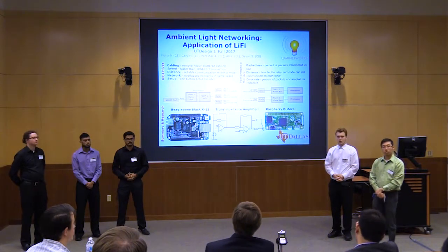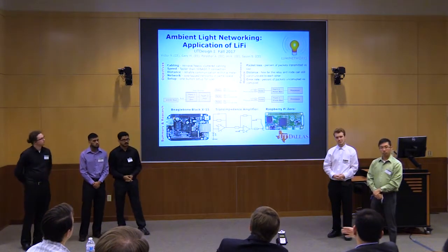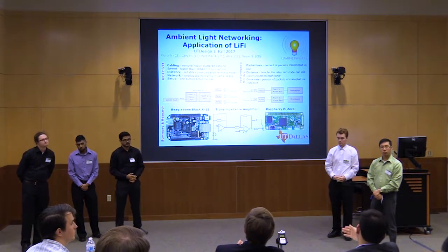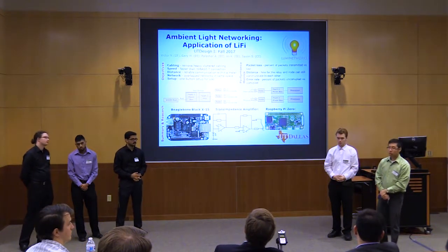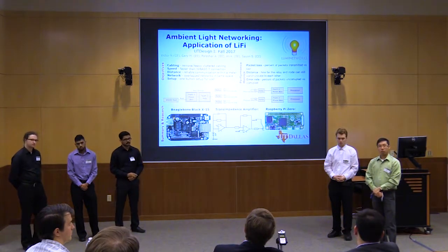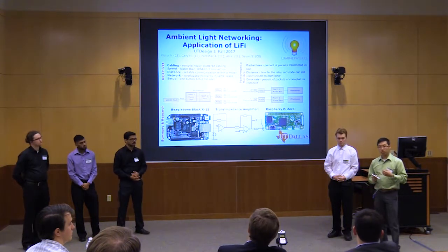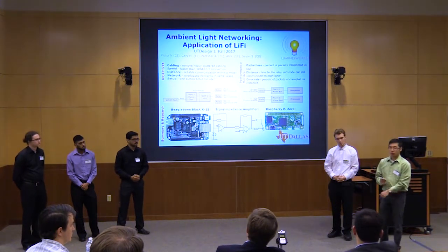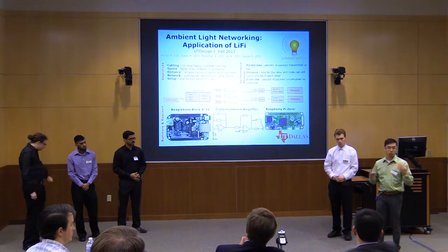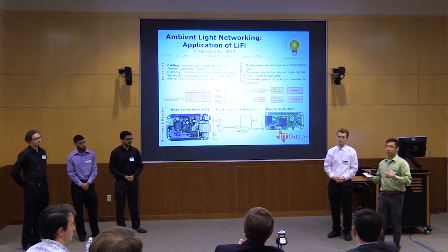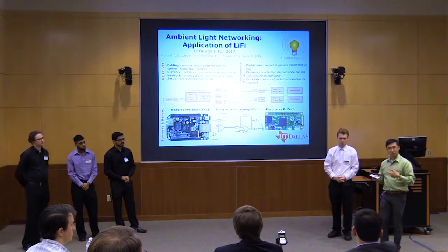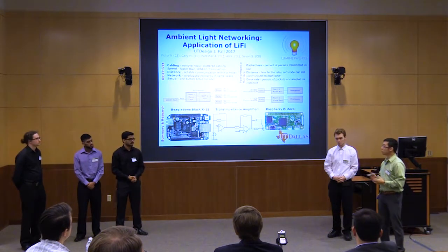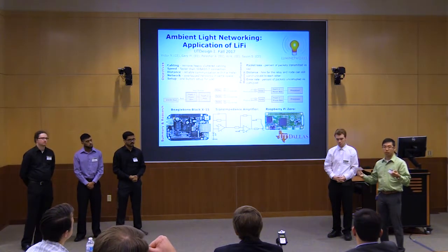Because LiFi is sometimes compared to Wi-Fi, especially in popular science, I think maybe understanding what the difference is between what you're doing and what just a regular Wi-Fi type device does would be good, just to be able to explain it. So you're asking if we're able to differentiate between Wi-Fi and Li-Fi? Sure. So Wi-Fi is basically data transmission over radio waves. Li-Fi is a term that's slowly picking up. It's where you're transferring data over visible light. So our system is using LEDs and photodiodes to transmit and receive light, respectively.